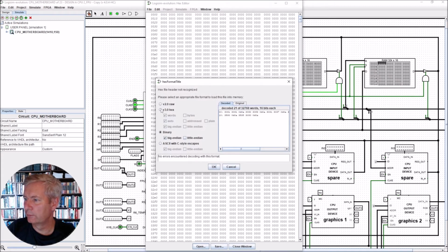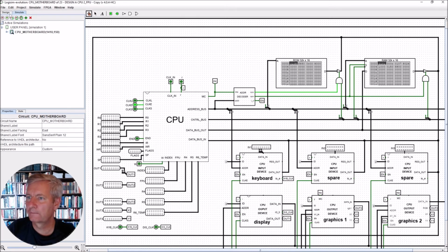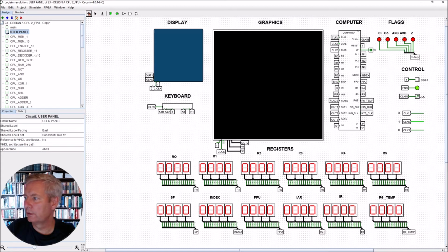And I do suggest you do this at least once to understand the whole process. Now what you can do is run through it one step at a time. So we can go through again, setting up the stack pointer and then jumping to the first address of the program and then working through the first instruction, which puts the value 12 into register R1,